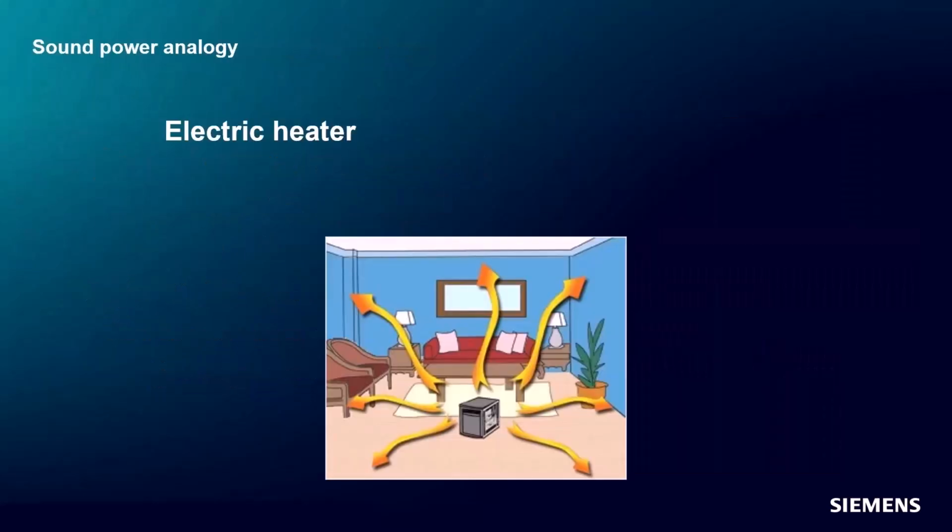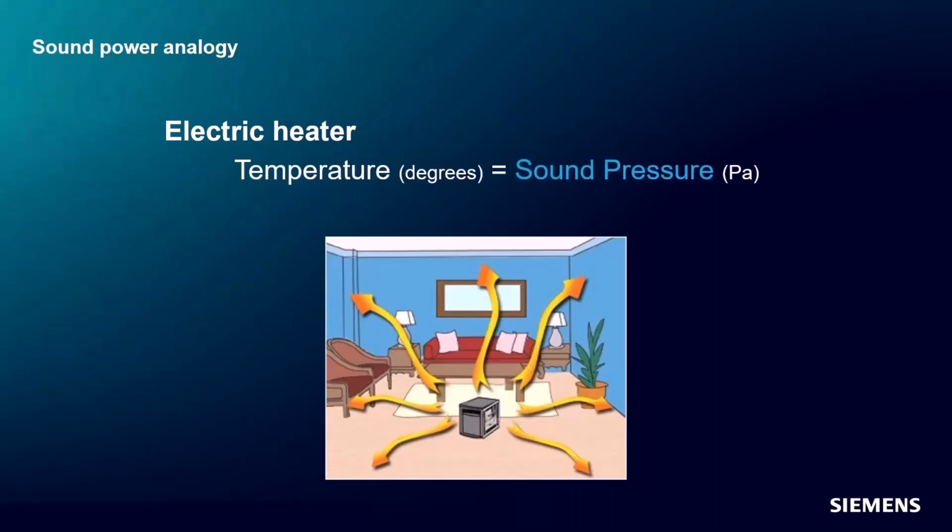If you take an analogy for sound power, suppose we have an electric heater in a room, and the heater will be radiating heat around the room. The temperature at a specific location in the room will depend on how close you are to the source, measuring the temperature using a thermometer, for example, and also which direction, whether it is facing forward or backward, things like that. Sound pressure is something similar to that. It is like the measurement of the temperature around a heater.